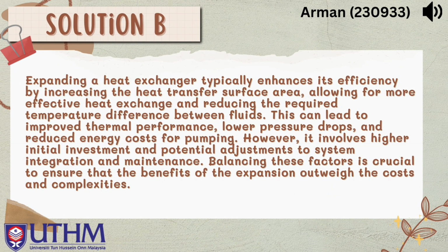Expanding a heat exchanger typically enhances its efficiency by increasing the heat transfer surface area, allowing for more effective heat exchange and reducing the required temperature differences between fluids. This can lead to improved thermal performance, lower pressure drops, and reduced energy costs for pumping. However, it involves higher initial investments and potential adjustments to system integration and maintenance. Balancing these factors is crucial to ensure that the benefits of the expansion outweigh the costs and complexities.